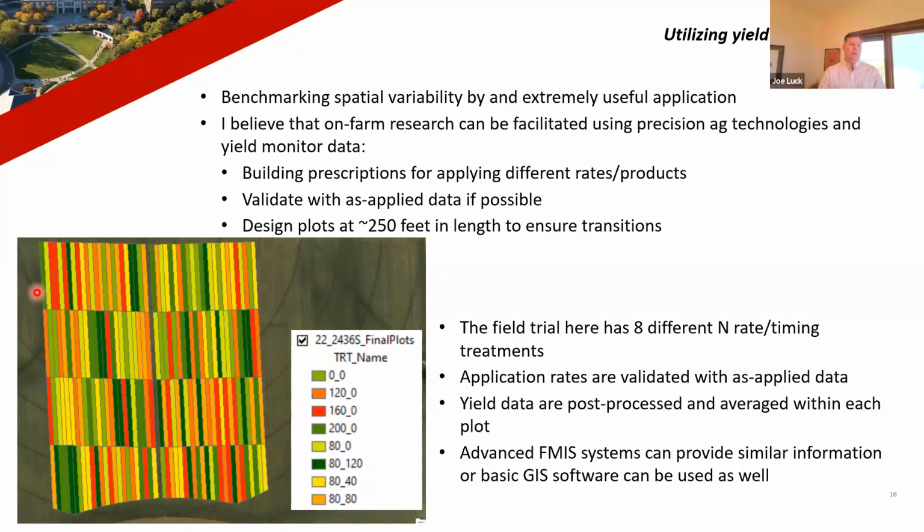If you can get about 200 feet of yield monitor data, studies in the past have shown you really need that because of the yield data variability. We talked about the flow through the machine, and that can take different paths. You really need about 200 feet to get an estimate that's going to match up really well with the scale weight. There have been a lot of studies in the past that have validated that. So that's how we're using this to try and maximize our field area.